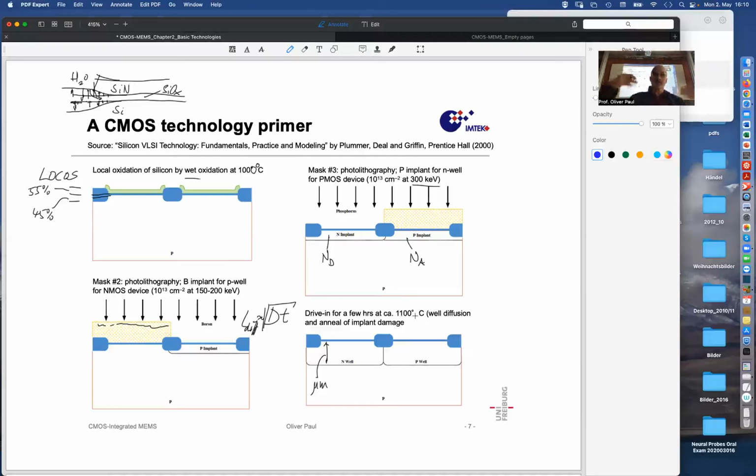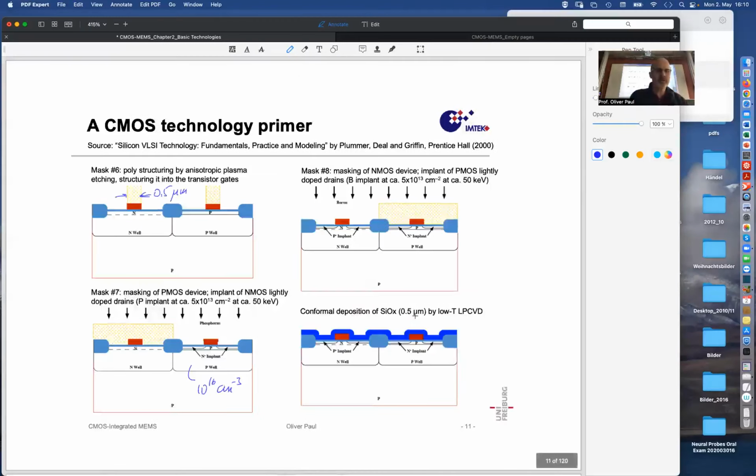And during that period of several hours at this temperature, the dopants can diffuse deep into the crystal. And we don't want any such deep diffusions anymore. We want them to stay close. So the temperatures need to remain lower and lower. Otherwise, we ruin what we would like to do. It wouldn't be a good idea to do the drain diffusion at the end, because then everything gets implanted very deeply, and all your trouble is for nothing.